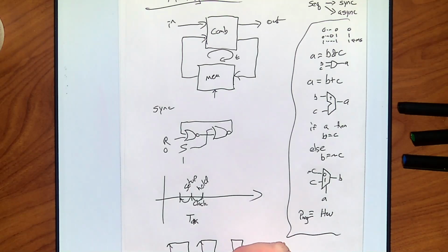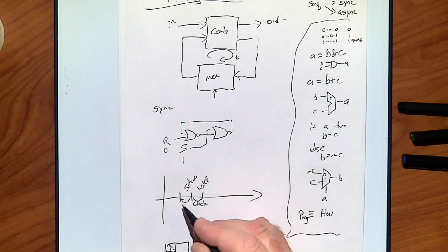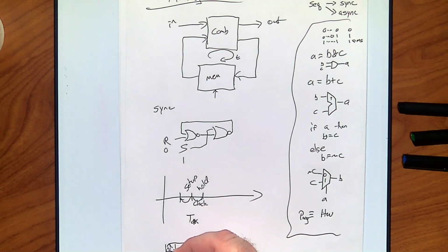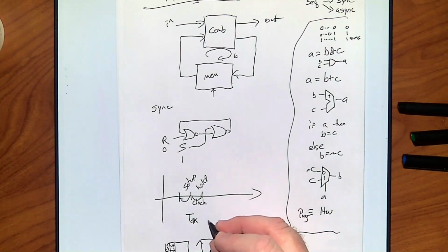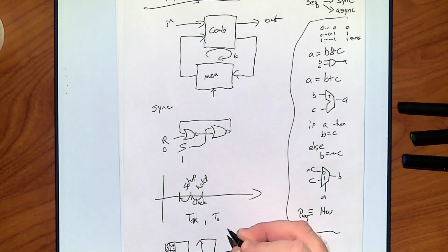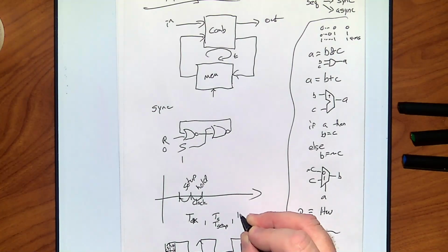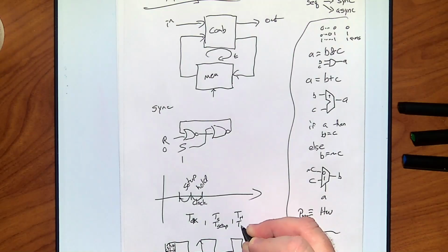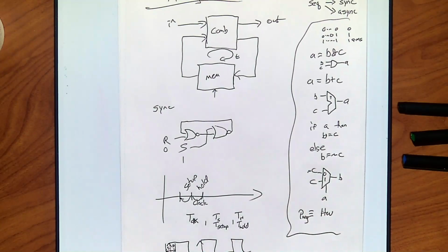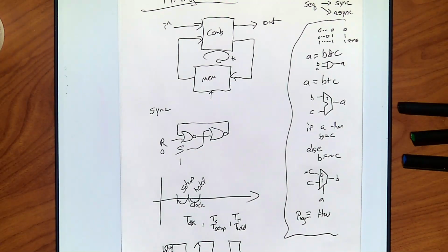If I was doing positive edge of clock, for each one of these, there's a safety margin that I want to put around it, which is what these are. I need a little setup time. I need a little hold time. We usually call these appropriately T_S or T setup and T_H or T hold. There. That's a little protection over here.